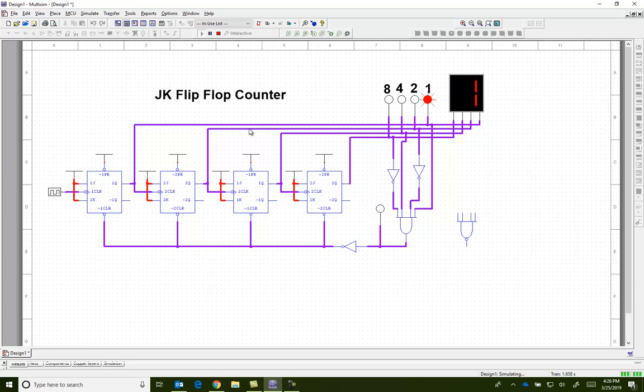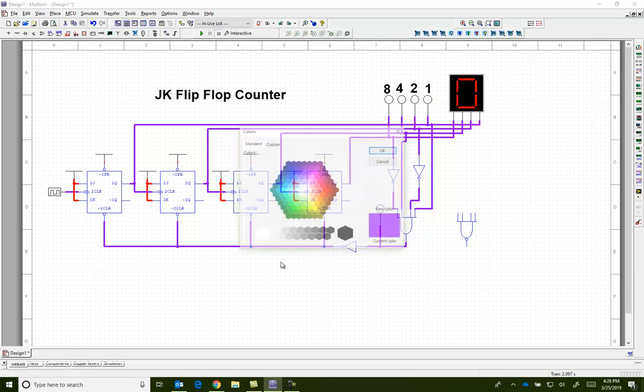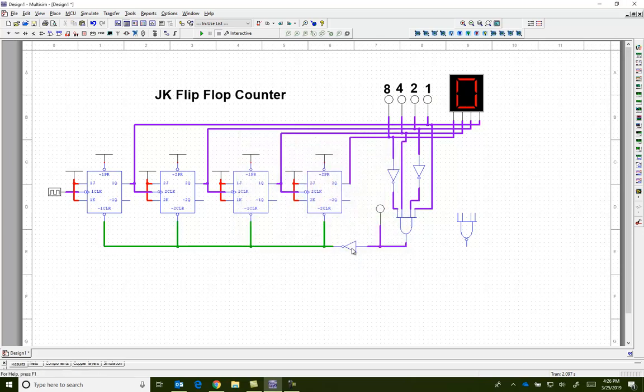So you have to remember that the clears of all these flip-flops are not synchronous with the clock. They immediately get a signal and they override. So let me see. This green wire, the moment the AND gate gives it a 1, inverted to a 0 so that it clears, immediately it clears. So yes, it's showing a 5, and then within a fraction of a second it says, don't show a 5, show a 0, 0, 0, and 0. So if I really want to count up to 5, what number do I have to put here so it doesn't override the 5?